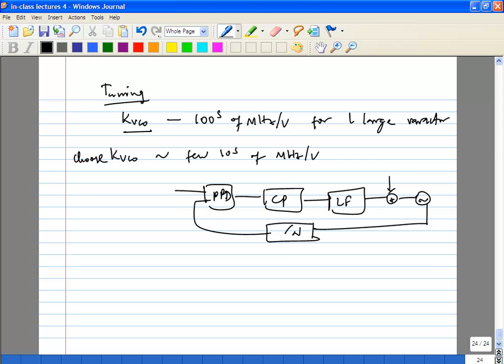If you have any noise or some harmonic or low frequency signal leaking into the VCO input, the larger the KVCO you have, the larger the gain to the output. So you want to keep that also small. You could have things coupling to the loop filter node after the loop filter. Obviously anything coupling in here will get attenuated by the loop filter, but anything after that will be a problem.